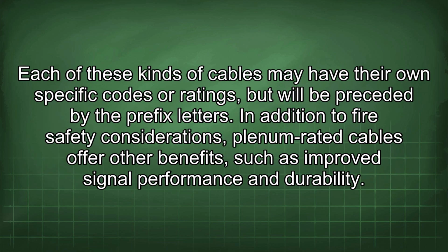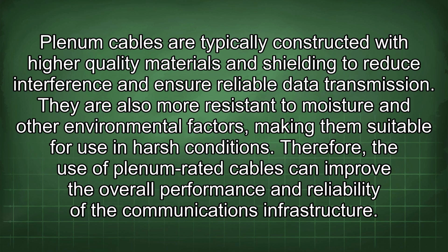Each of these kinds of cables may have their own specific codes or ratings, but will be preceded by the prefix letters. In addition to fire safety considerations, plenum-rated cables offer other benefits, such as improved signal performance and durability. Plenum cables are typically constructed with higher quality materials and shielding to reduce interference and ensure reliable data transmission. They are also more resistant to moisture and other environmental factors, making them suitable for use in harsh conditions.